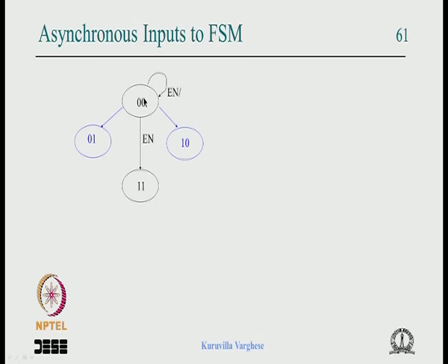Okay. Now because of the path delays, difference in path delays, this will be sampled at different points in time, and you can imagine sometimes it may happen that the Q1 transits to 1 and Q0 remains there because it is asynchronous, or the opposite can happen. The Q1 remains in 0, that means mistriggered, it retained the previous value, but the Q0 has transited. So it may happen that instead of the valid state 1 1, when the clock comes it transits to a kind of invalid